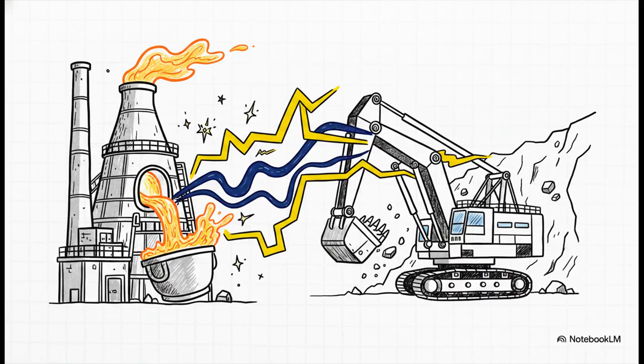Look, you aren't going to throw a compound filter on a standard HVAC system. But if you're running an extremely high-power, complex industrial site, think a massive steel mill or a sprawling mining operation, this is your ultimate solution. Those sites have heavy, steady baseload harmonics mixed with violent, fluctuating harmonic loads. Only a hybrid system is tough enough and smart enough to tackle that kind of extreme environment.